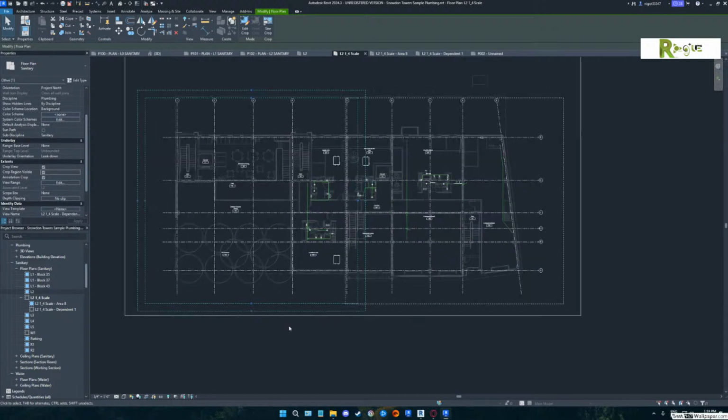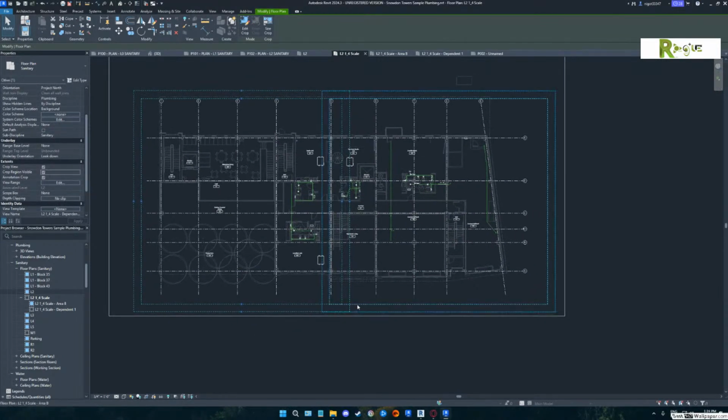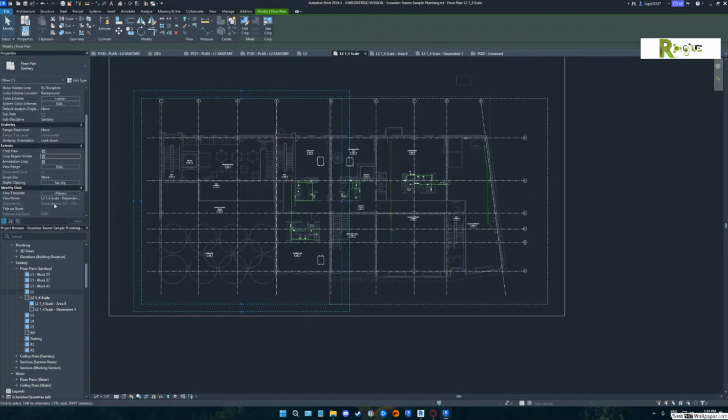Now here's where you can actually name these a little bit better, because you can see the one you got selected right now. That's actually the one you want to make area A. Now, the way I would name it is, you see how you have it selected? Look at your properties at the very bottom of the properties box. Very bottom, last slot. You see that view name? And then you would name that area A. Dragged a little bit too far off the screen. There you go. And just move your cursor onto the screen and look at how it named it.